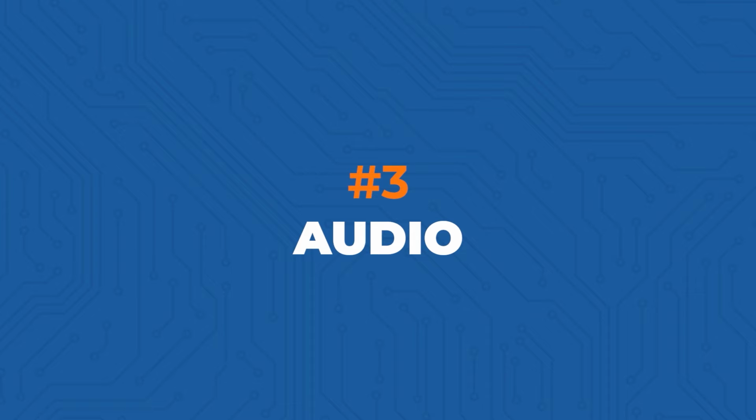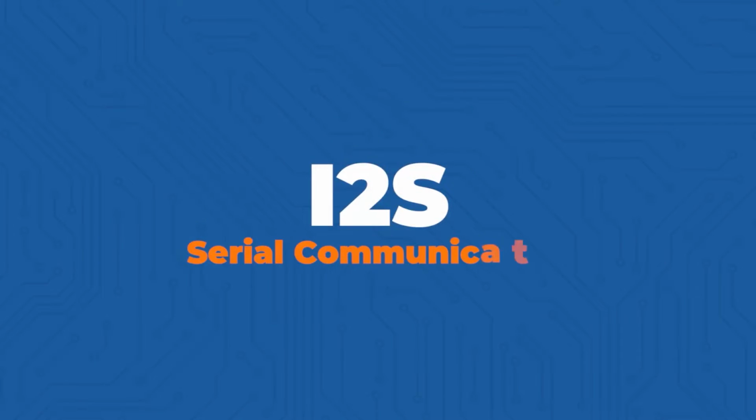For instance, use a microphone that already has an analog to digital converter built into it, and it just outputs in an I2S serial communication format. I2S is just a serial communication protocol specifically for digital audio data. If you use a microphone that outputs the audio as digital audio data in I2S format, you can just send that to your microcontroller or whatever, without any concern for noise pickup. But for any analog audio, you want to definitely be very careful on the PCB layout.